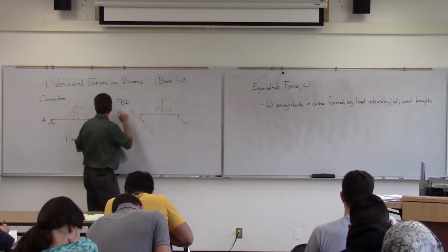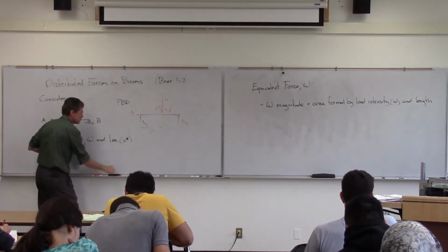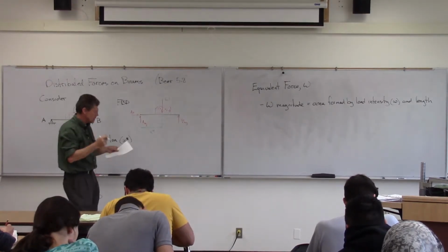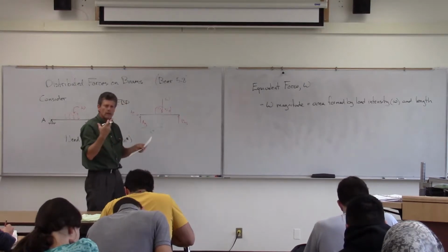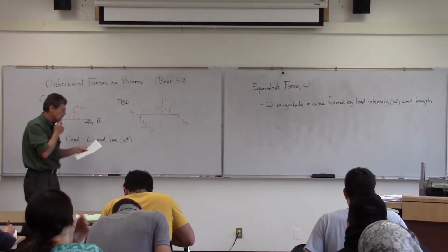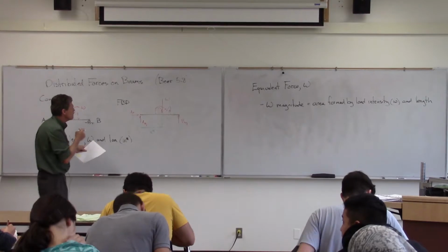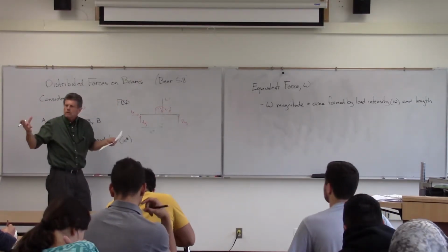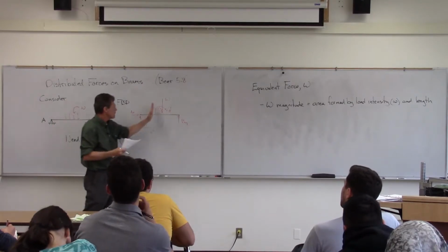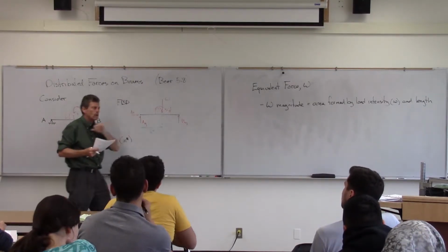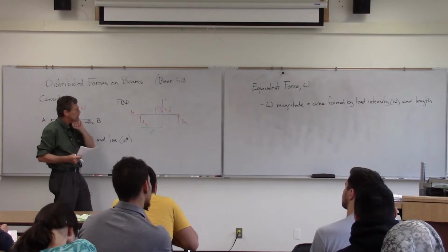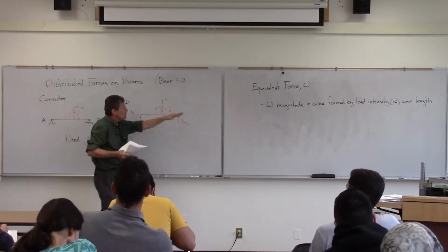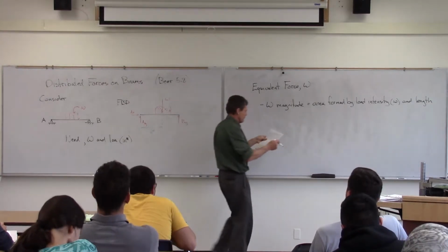The load intensity is this little w. That's supposed to be a big W there. This little w is describing my load intensity, and load intensity is given in terms of force per length. But what we're going to find is we're just going to have to calculate this area. And we just got done doing that with a centroid, right? I could take this, and if I knew the equation for that, do vertical strips, do a quick calculation. And I've got, instead of an area now, a magnitude.